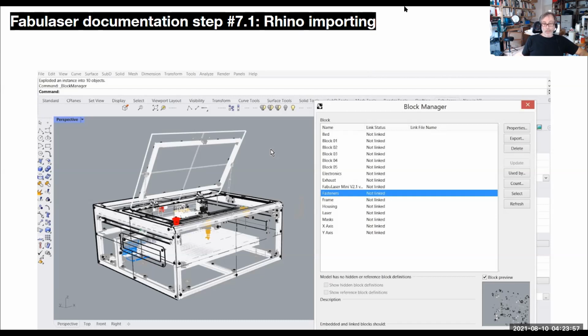And the thing is, if you make it in Fusion 360, all the parts like screws, you will not draw each screw separately. You will have one screw and you multiply it. And each time you multiply that screw, it becomes like a block instance. It's like a virtual link to the mother screw. And you have to explode those. You have to get rid of those links and make sure you have that one screw and its 100 children, make them like individual objects.